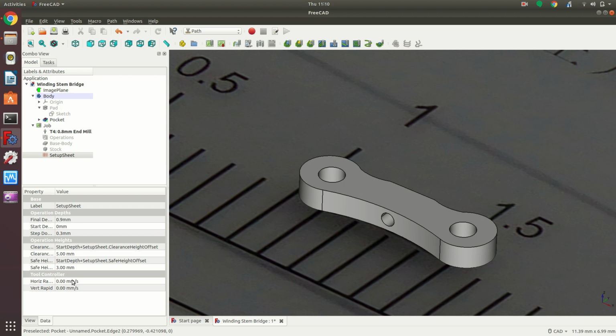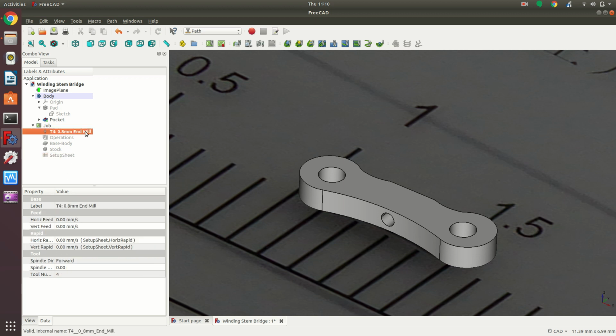Okay. Now, what we also have to define is spindle speed. With that sort of tool, we go full pelt, 24,000. And we define a horizontal and a vertical feed. Horizontal feed is milling around the shape. And again, in steel, I would say we go about 0.1 max. But this is brass. We can probably go 0.2 millimeters per second.